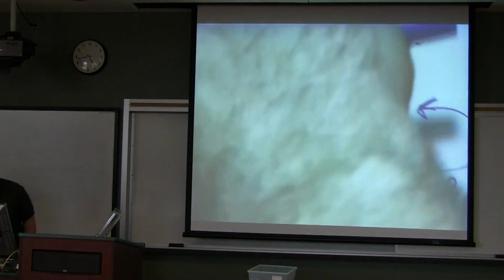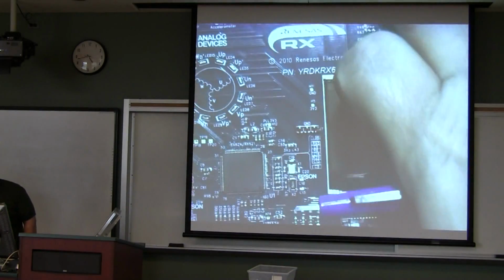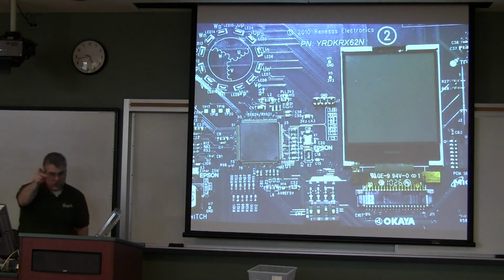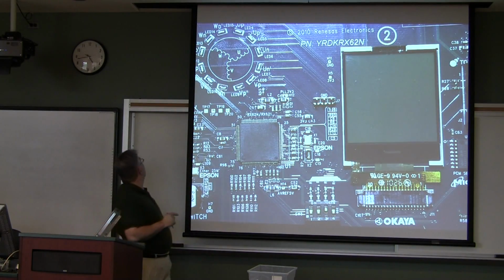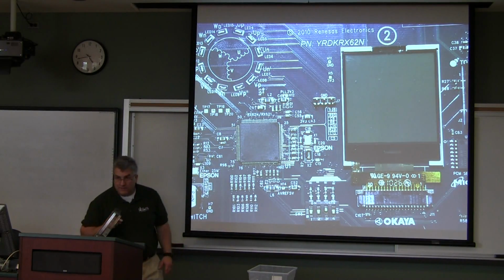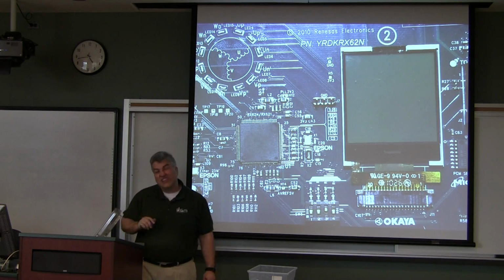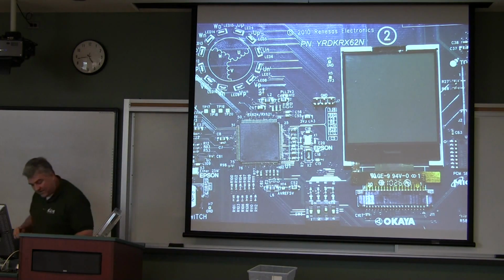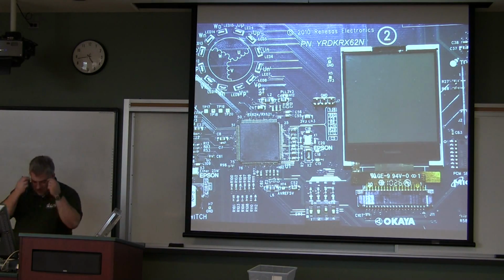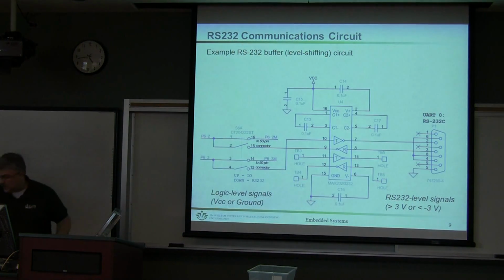Now, what that means is that when you want to communicate, obviously all you have to worry about is logical 0 and logical 1. You're telling the serial port, I want to send out this byte. And you know what? The hardware itself is going to take care of the specific signals that you're going to send out.